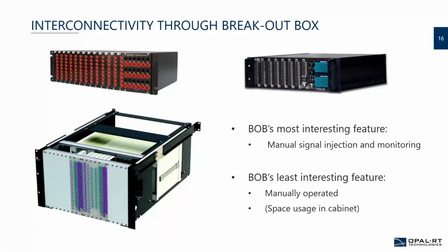With an oscilloscope or multimeters or whatever tools, the breakout box lets you have quick access to the signals and measure them. Same thing for adding a quick filter: you have noise on the signals for some reason that you didn't expect. With a breakout box, you can mount a small prototype setup there to do a filter, and maybe that will correct and adjust the test bench.